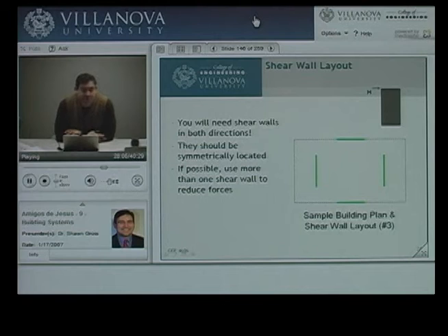What happens oftentimes in skyscrapers is really a variation on this theme, where elevator shafts make good shear wall locations, often at the core of your building. So the bottom line is there are a lot of options, and you have to look at your particular structure, see what the architectural requirements are, and try to meet those as much as we can, such that we don't have to change the details that are given to you.